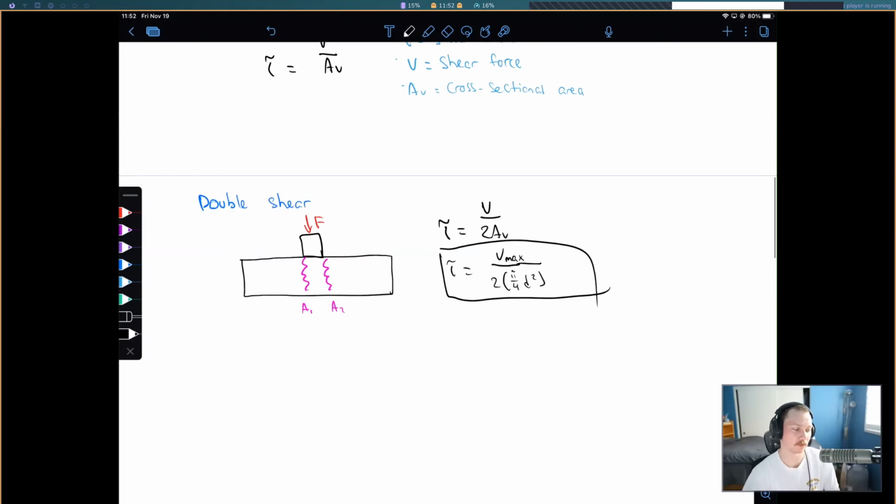And then the next thing we're going to talk about is the theoretical shear strength. The theoretical shear strength was made from empirical formulas, and they're kind of crude approximations for what the shear strength is going to be. It's going to be a constant multiplied by the ultimate tensile strength for that specific material. So we're going to calculate that theoretical value and compare it to the experimental value like we often do.